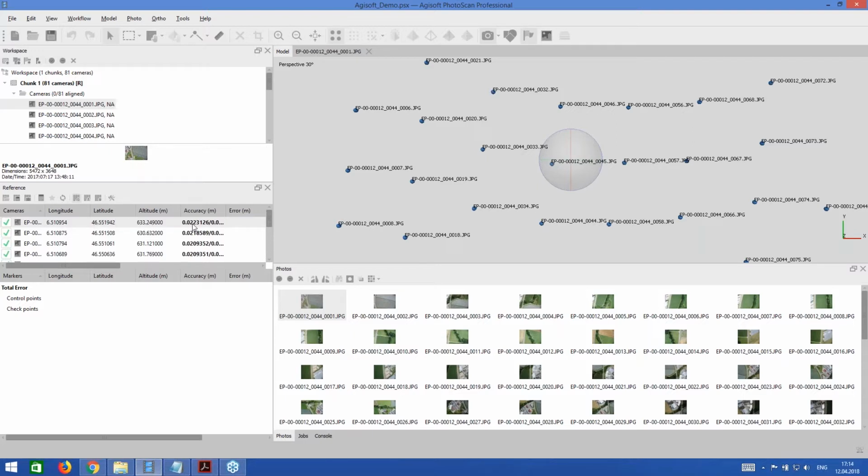We see that for this data set, all camera positions were measured with the accuracy of almost 2 centimeters, which is pretty high thanks to RTK system used by EB survey platform. Definitely, the accuracy of the input data matters significantly for the results of photogrammetric processing. That's why it's good to use an RTK dataset.